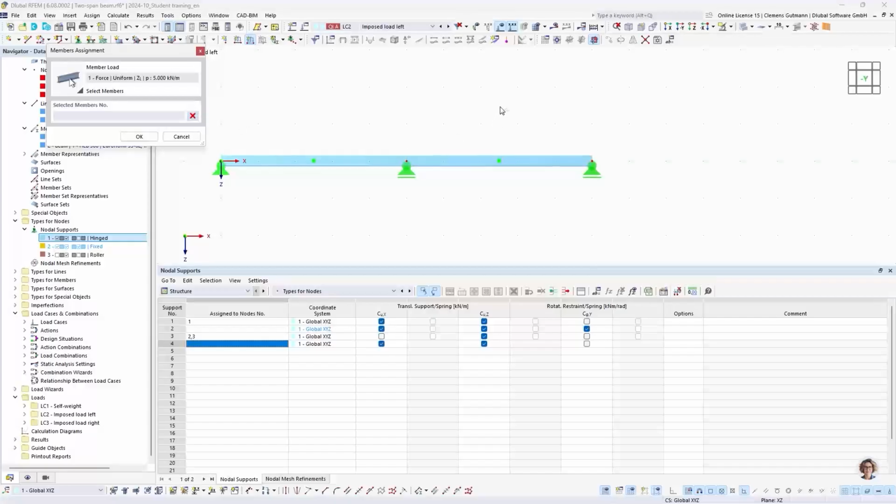Deselect this. If I do the same thing by drawing right, it is not selected. So when the orange rectangle is used as selection, only objects that are fully inside that rectangle are selected. And if I do the same to the left and use the blue, also members that are only partly in that rectangle are being selected.